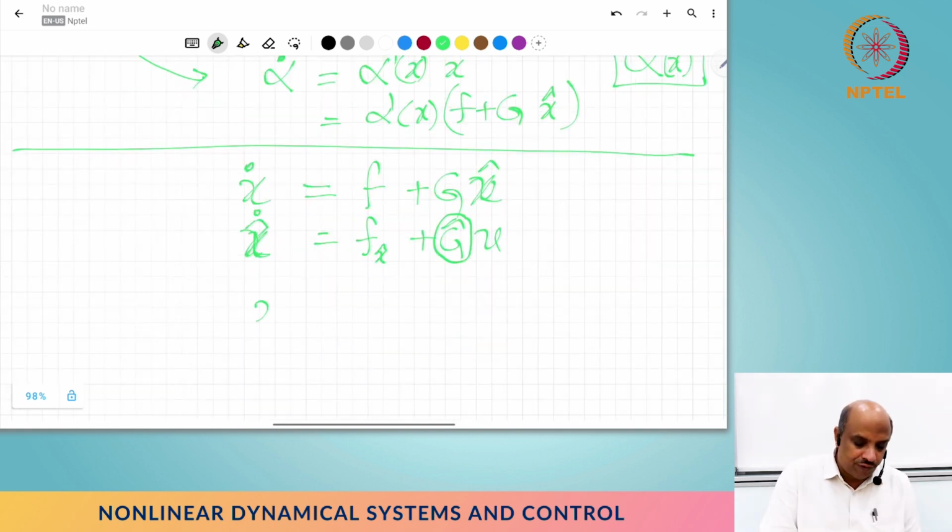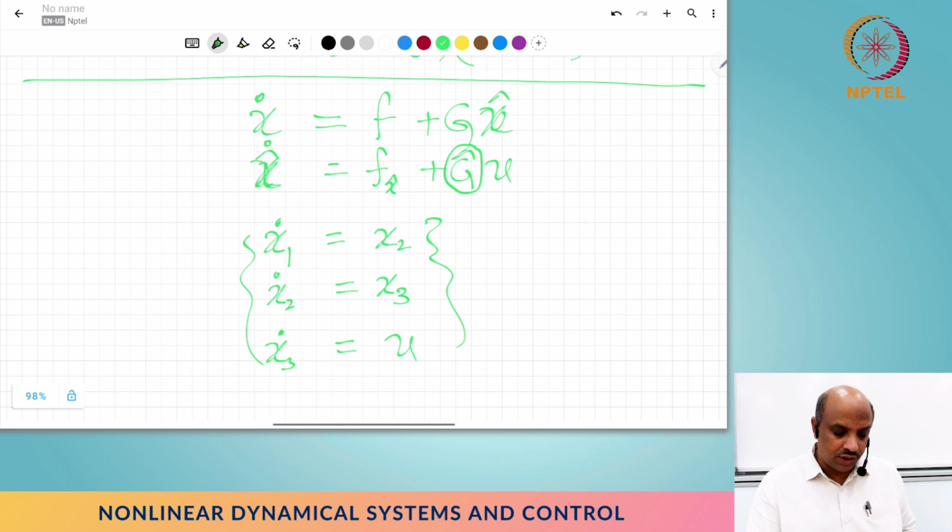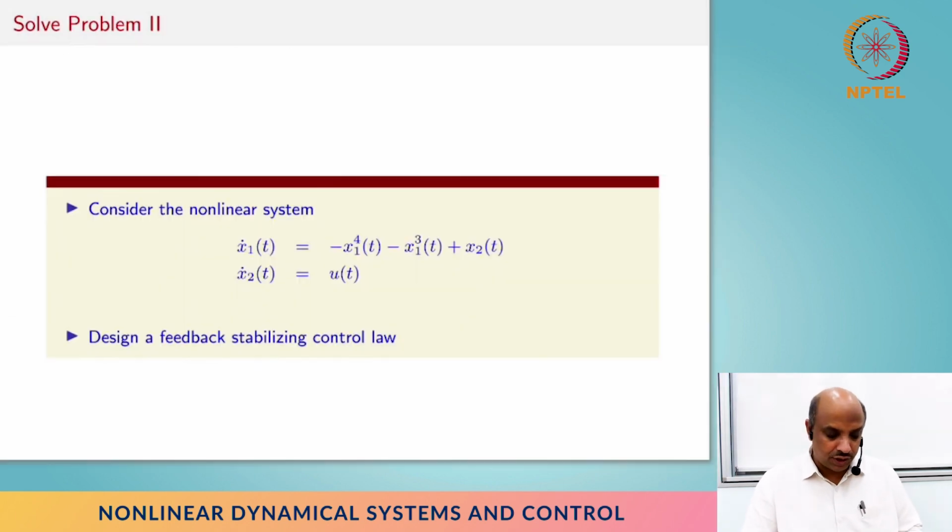Now suppose I had something like this. So what do I do? Well, I treat this first problem as if I'm controlling with this as u, and then once I have that, I rewrite this problem in such a way that I consider that as the first part, and then basically redesign. So this cascade structure, I would urge you to try to solve this particular problem: how do I imitate this process for even more cascades? So that is how it works,